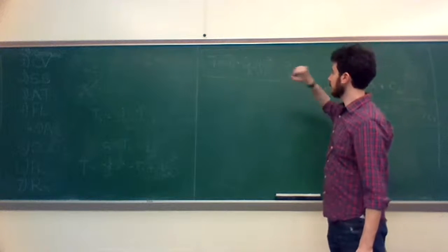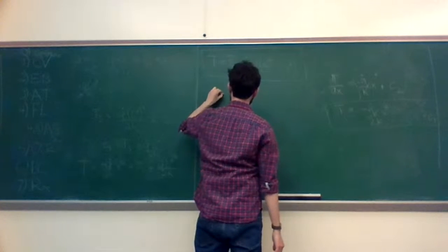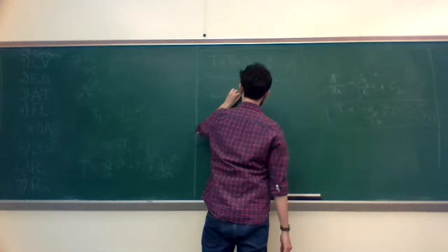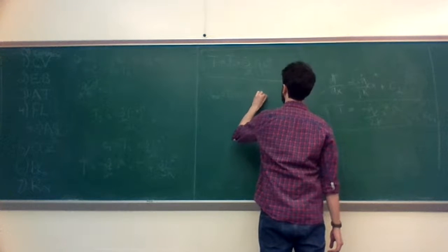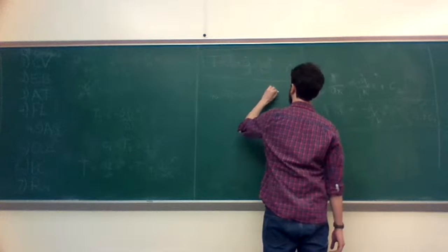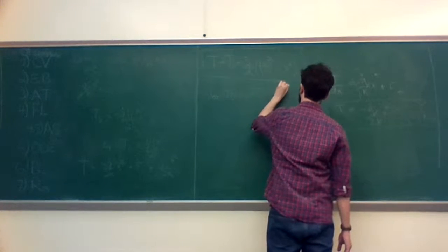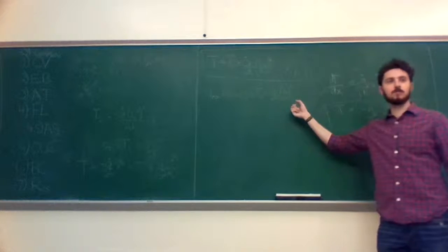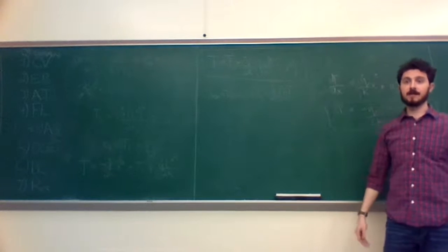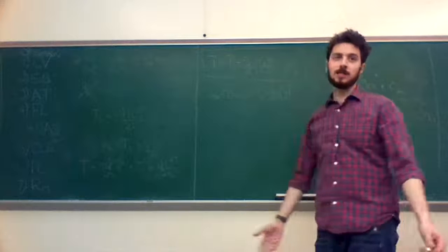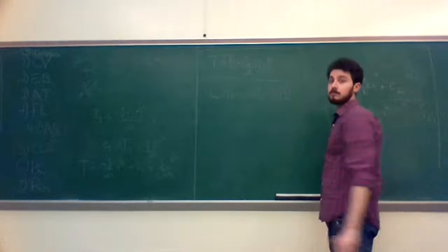What is it though? We plug in x squared equals 0, and you get T max, which is just equal to T at x equals 0, which equals TS plus Q star over 2k times L over 2 squared. Now the funny thing is, what's the units of this whole term? Kelvin, or Fahrenheit, or Rankine, or whatever. It's in units of temperature. So this is the temperature, right?